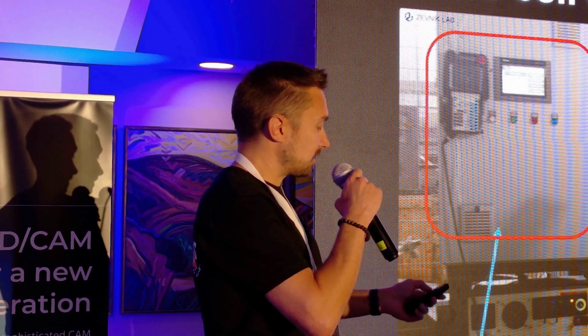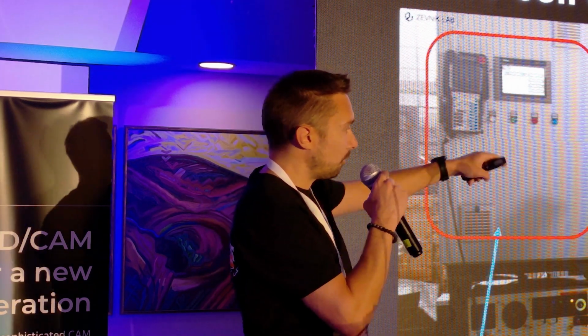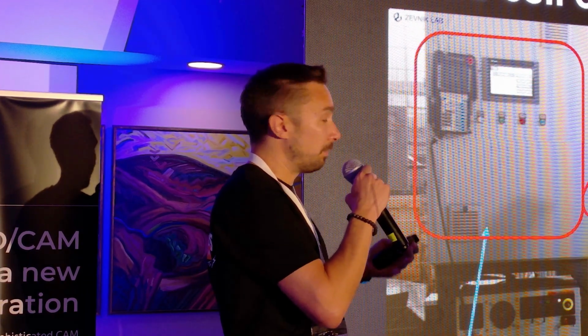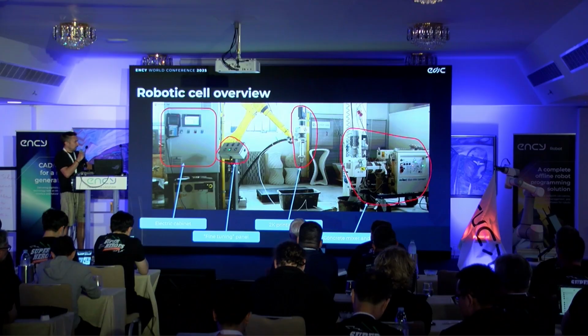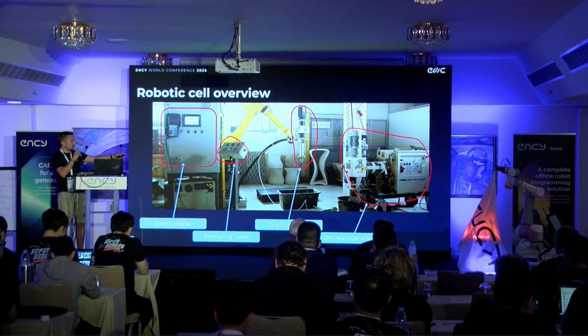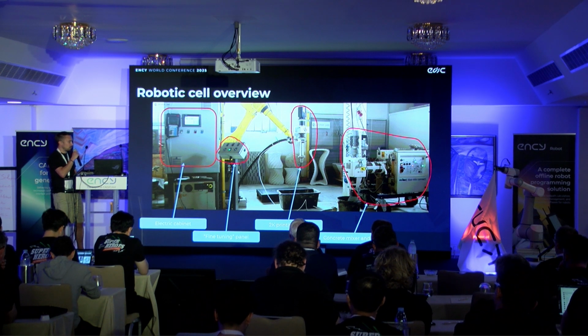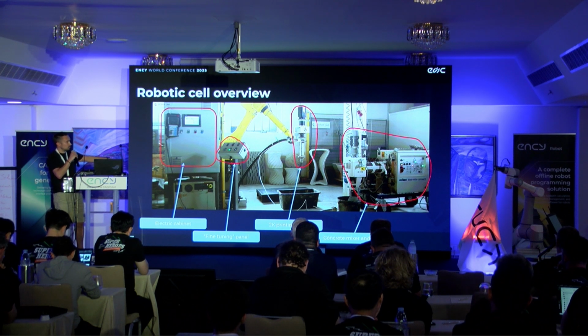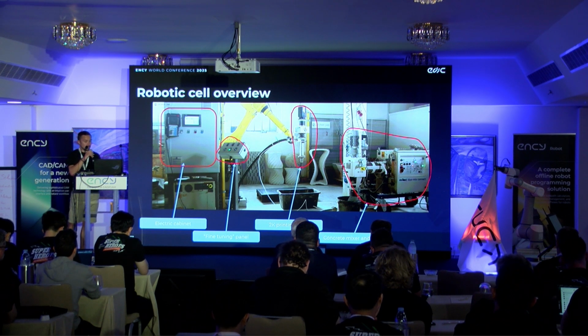And to mix these components together, usually the components are mixed right at the nozzle. In this case, the nozzle is a little bit bigger than usual, when you just have a tube at the end. The fourth important component is the concrete mixer and pump, which mixes concrete with some additives and pumps it to the printing head.